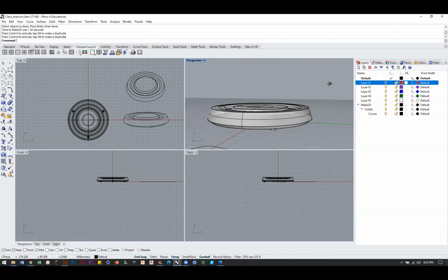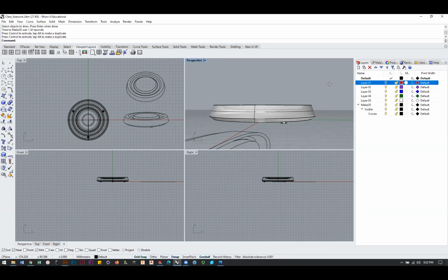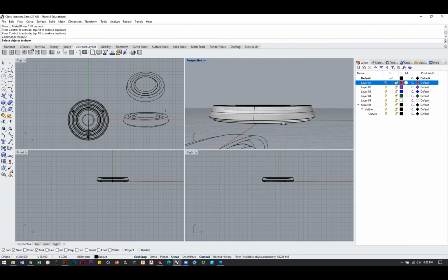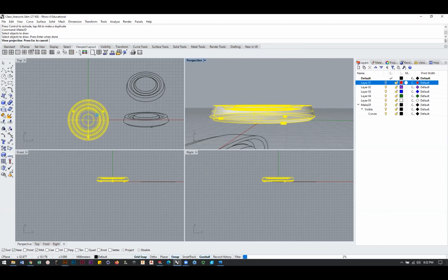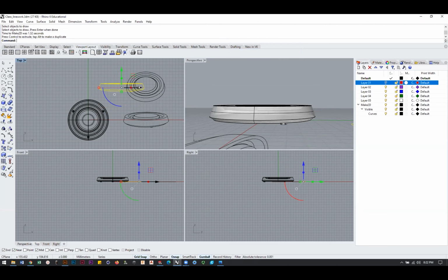If you want to look at it with just a super slight little angle like this, like you can hardly see whatever, that's like a 0-degree ellipse right there, and you run Make 2D and you select it, hit it again, it spits out that same exact angle. Okay. So this is a really cool idea that you can get editable line work from any angle that you can look at your model in.